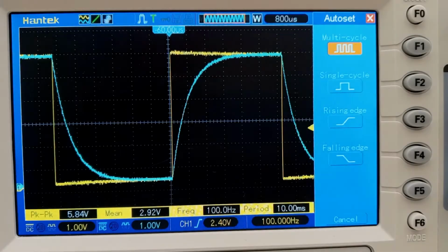We can measure the time constant directly from the shape of our signal and compare to this expected value. In this zoomed-in view on the oscilloscope, each box is equal to 1 volt in height and 800 microseconds in width. We can use this to take values directly off the screen and plug into our equations to find the time constant. We can then compare this to what we calculate from the component values.